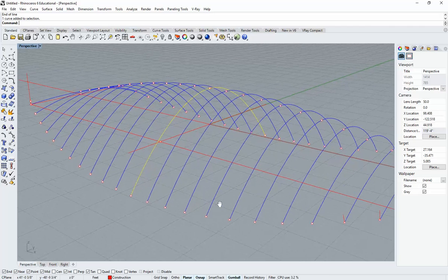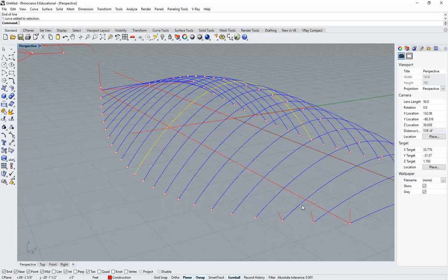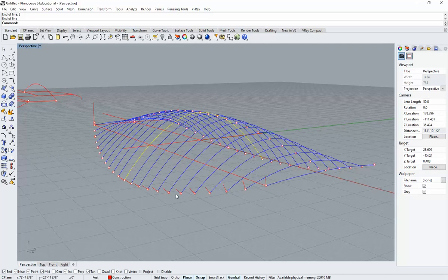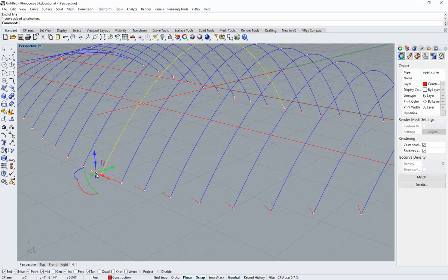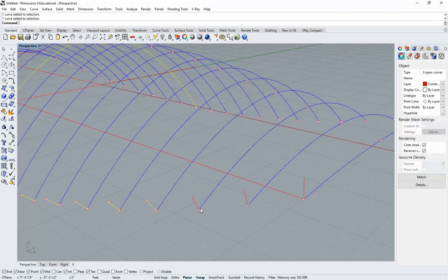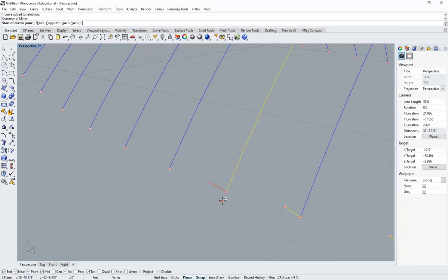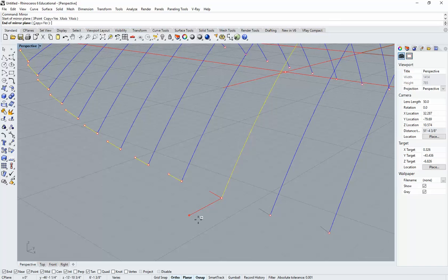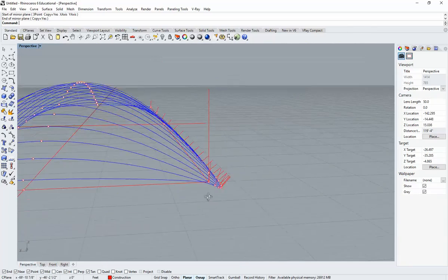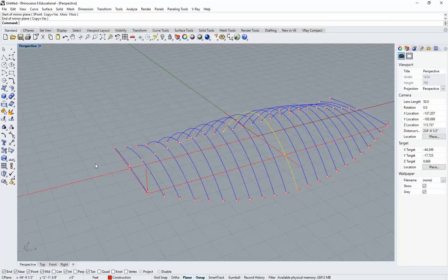All right, so why don't you guys go ahead and do that, and I'm going to pause the video so I can finish mine as well. Okay, I'm going to turn this back on. You can see that I've modeled all of these. And I'm going to select, not the center one because I don't need to mirror that, just the rest of them that go back here to the beginning. And type in mirror. And now I can mirror everything off of that point of our center line. You can see, and I'm going to hold shift down in the -y as my axis, and there we are. So I can save myself some time because this is a symmetrical form. Okay. Delete that.